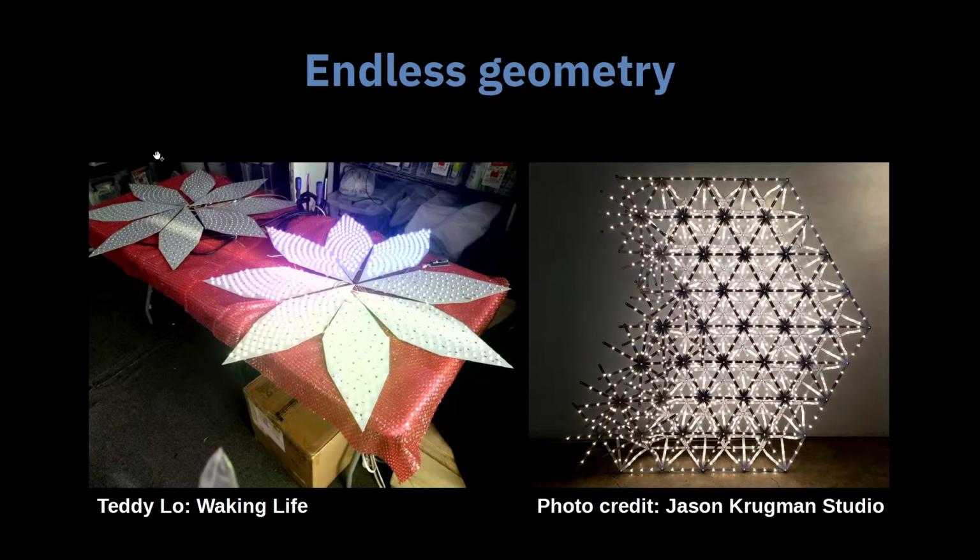And for a long time, I was just standing there. Every time we would do it, I'd spend 2 hours, and I'd open the design up in my schematic editor, or in my PCB editor, and I'd select everything, drag it over 2 millimeters, select the next thing, drag it over 2 millimeters, and then the last one is another millimeter. And anytime we make a mistake, it's 1,500 euros to make a new set of boards. So it's really annoying, and it's a very painstaking process.